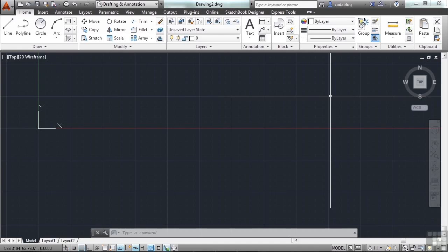In an earlier section, we discussed how AutoCAD uses a Cartesian coordinate system. Sometimes we need to create nodes at specific coordinates, not a line, not an arc, or a circle. These are known as points, and there is a command that will help you draw a point. Its size doesn't matter because a point, by definition, has no size. It's only a marker or a node for a specific set of coordinates. A good example of using points would be that of a surveyor locating the corners of a piece of property.